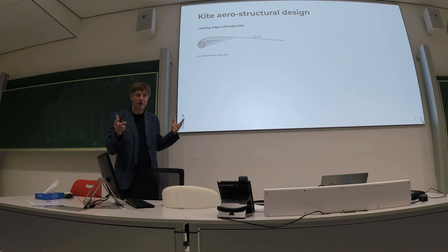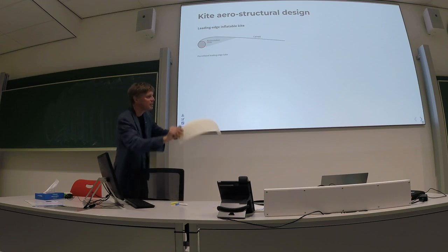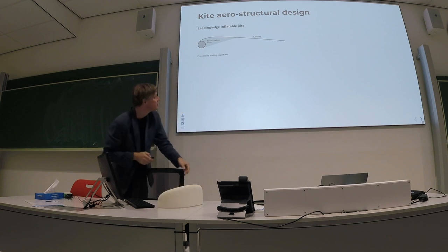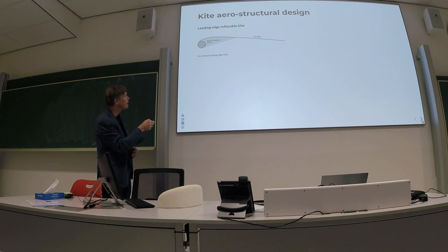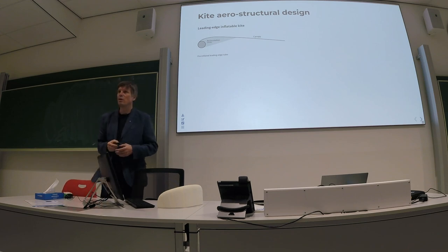These were 3D views. Now we look in 2D at what's special about these kites. That's the LEI, leading edge inflatable kite. It's basically a cut through the wing here, or any other span station. You see here the tube and the canopy. The airflow typically has this recirculation zone. Other than a closed wing profile, the flow separates here, even at low angles of attack, and creates a recirculation zone, which is giving us a hard time when we try to solve the aerodynamics.